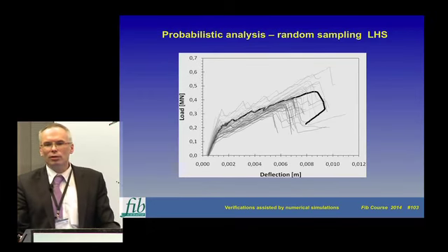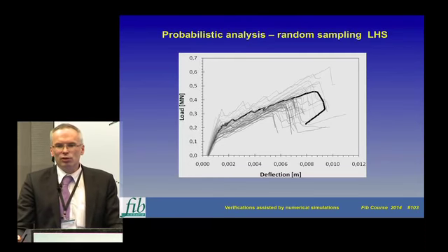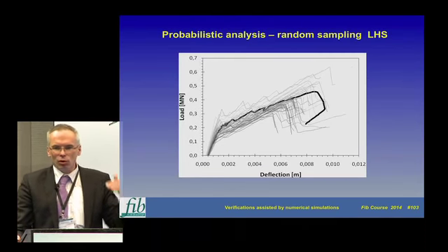Well, typically when we do this kind of analysis, as a failure we consider really the collapse. As you see here, we keep increasing the load until we see that the load does not increase anymore, it is going down. Of course you need some special nonlinear solution techniques to be able to go into post-peak.